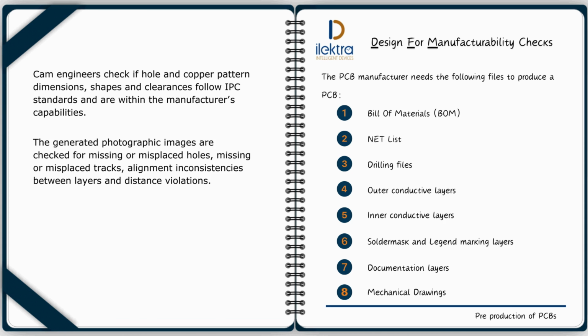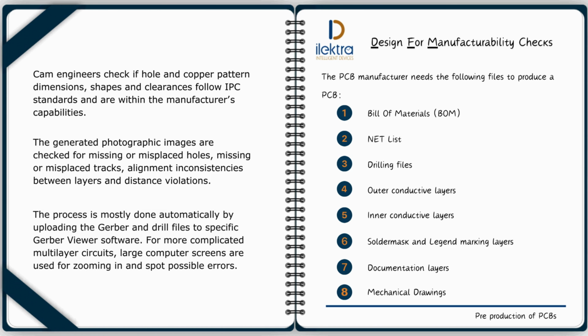The generated photographic images are checked for missing or misplaced holes, missing or misplaced tracks, alignment inconsistencies between layers and distance violations. For simple low-density circuits, the process is mostly done automatically by uploading the Gerber and drill files to specific Gerber viewer software. For more complicated multilayer circuits, large computer screens are used for zooming in and spot possible errors.